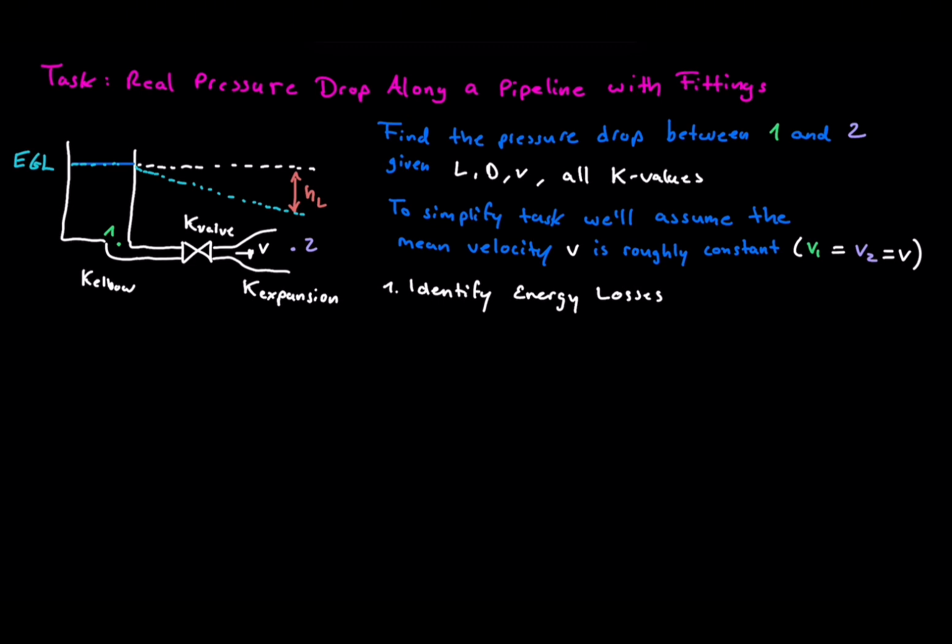Because the pressure taps are placed in equal diameter straight runs far from the fittings, where the velocity profile is fully recovered. The flow rate is steady and incompressible. So with equal cross sections at both taps, continuity guarantees the same average speed.